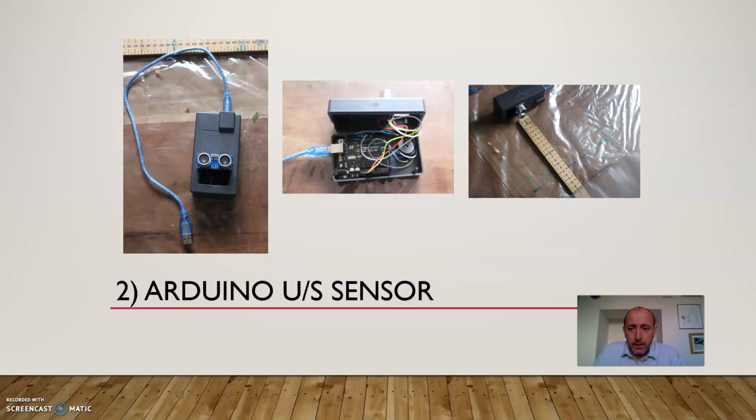So this is a homemade sensor. Again, I had plenty of time over lockdown to play around with these sensors. Inside, you can see it's an Arduino Uno board, not from Arduino, but a typical equivalent board. I put a small piezoelectric speaker in here so that every time you collect data, it beeps at every measurement along the way. We've got the ultrasonic sensor here. I included this in the box to hide the electronics inside the box. And this is our USB cable that we're going to connect to our laptop to record the data.